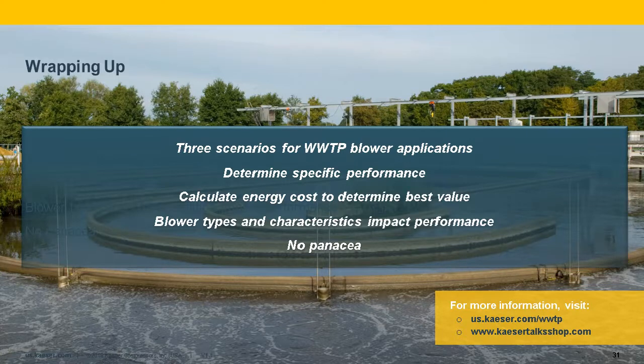Excellent. And does this work for other technologies like turbo blowers? Yeah, the analysis would absolutely work for turbo blowers, lobe blowers, or screw blowers. The difference is going to be how the data is worked out in the evaluation. So getting the data from the manufacturer, you can still populate your model as we populated it with the lobe blowers, and I think that ultimately this would give you the most representative comparison across technologies.